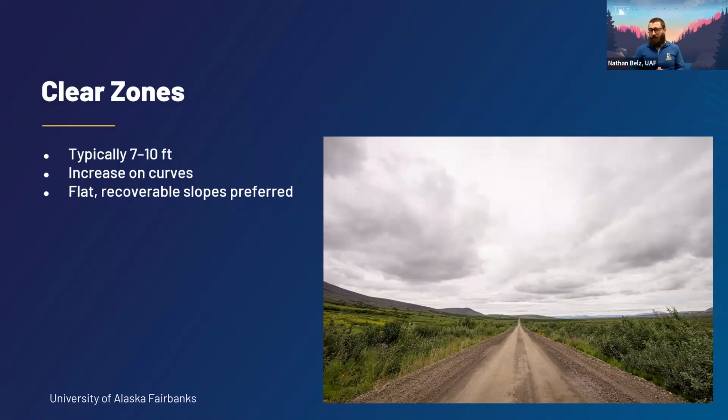Typically, these are going to be 7 to 10 feet, which is commensurate with the design speeds. But we would also want to increase those by about 50% on curves. And if possible, flat recoverable slopes are preferred. A flat recoverable slope would be something 4 to 1 or shallower.